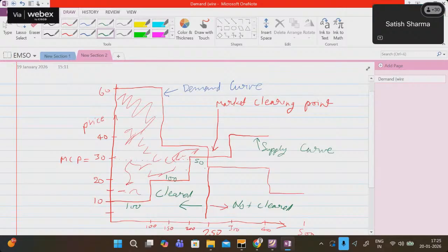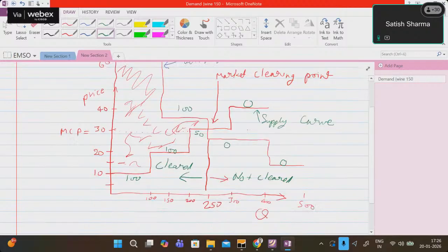But same, if you talk about the demand point of view, so this first term was 150, I think. So demand 1 will be getting 150 megawatt, demand 2 will be getting 100 megawatt, demand 3 will be getting 0, demand 4 will be getting 0. Generator 4, which is beyond this market clearing point, will be producing actually 0. So it is willing to produce 100 megawatt, but after the market clearing algorithm is performed, the output should be 0. Okay, so we have solved this one.